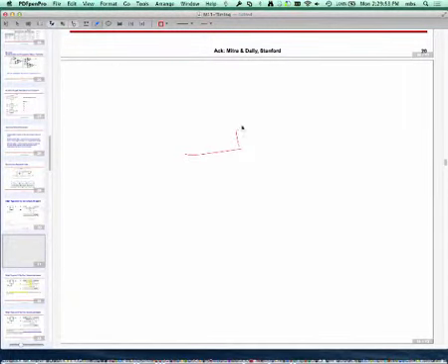Let's say this is my clock edge. Now let's consider a setup time of, say, 5 nanoseconds. That basically means that in this 5 nanosecond interval, things cannot change, so D can change before it, but here it should be stable.